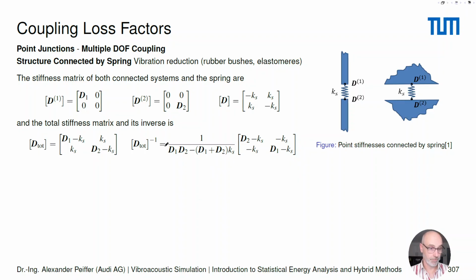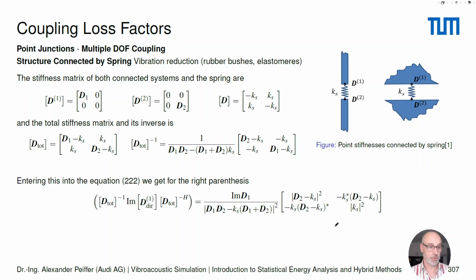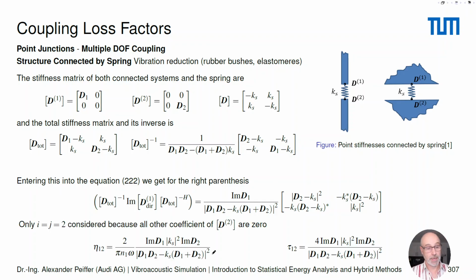If we do so, we have now again everything on board to calculate the transmission coefficient and the coupling loss factor, which will be done by this famous total stiffness triple matrix multiplication, and we would finally end up with this slightly more complicated expression. And dealing with all the mass and saying that we can neglect some of the different, let's say, indices, we get this expression here.